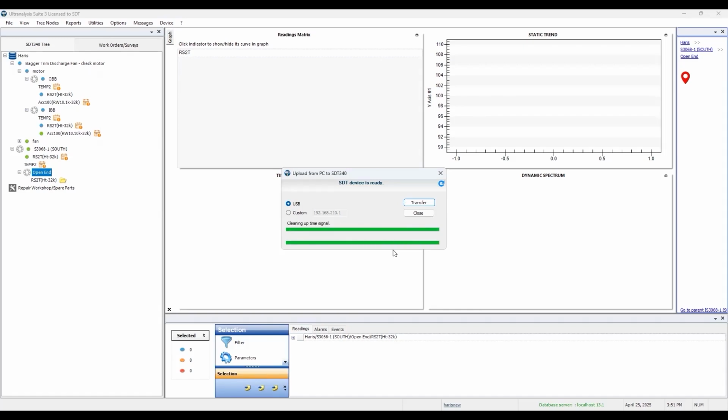And the way that open-ended measurements work, and it's especially useful for taking a measurement where you're waiting for an event to happen. So for example, if I was doing a steam trap inspection and I'm waiting for the steam trap to purge, I don't know if it's going to happen 30 seconds after I start recording or 2 minutes after I start recording.